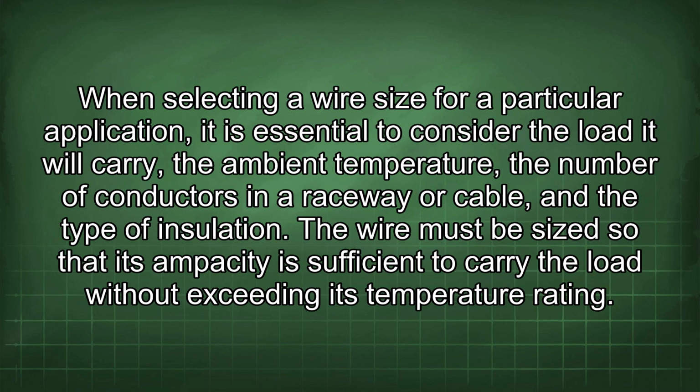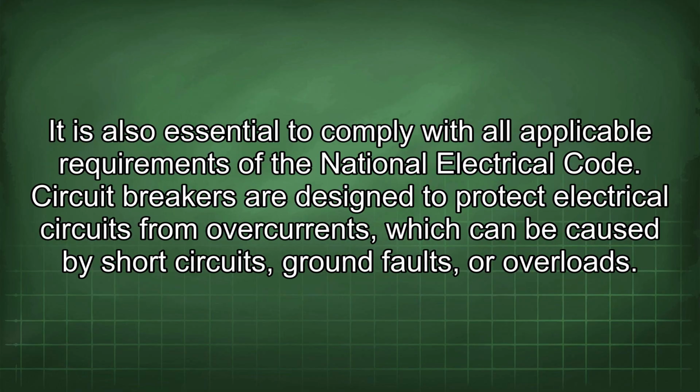When selecting a wire size for a particular application, it is essential to consider the load it will carry, the ambient temperature, the number of conductors in a raceway or cable, and the type of insulation. The wire must be sized so that its ampacity is sufficient to carry the load without exceeding its temperature rating. It is also essential to comply with all applicable requirements of the National Electrical Code.